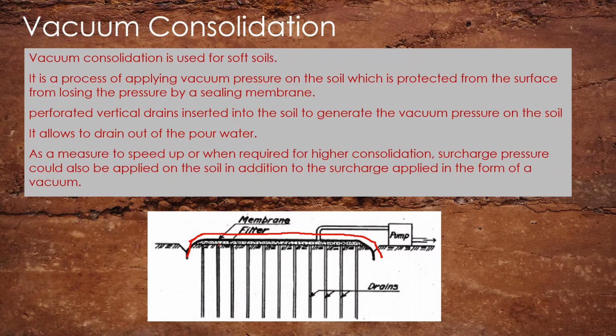In consolidation, when we apply pressure on the soil, the water will release from the clay soils, or the cohesive soil, to the outside. With the water release, the settlement occurs. So here also we apply the same concept. You apply the surcharge there, and we apply the vacuum pressure. Then with that you remove the water, and you get the required settlement.